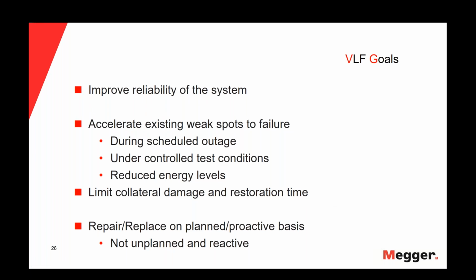So the goals of the VLF test are to improve the reliability of the system and accelerate the existing weak spots to failure, of course during a scheduled outage, under controlled test conditions, and at reduced energy levels. This last is very important. Having a fault at reduced energy levels is not the same as having a fault when the cable is in service. The big difference is the amount of energy that will be liberated through the fault. When the cable fails during service, I will have a higher amount of energy, and for that reason I could have collateral damage. When the cable fails during a VLF test, the energy is smaller, and for that reason I have limited collateral damage. The other goal is that we will repair and replace on a planned and proactive basis, not on an unplanned and reactive one.